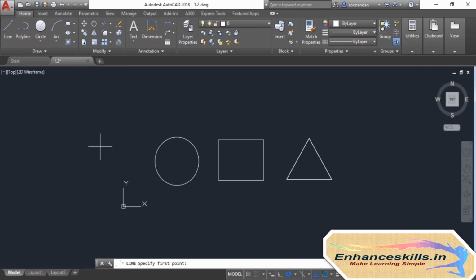Once the command is active, you'll notice that its name and also the instruction will be visible on the command line, and the cursor will change into this point selection cursor or into a pick box, which is similar to this. In order to exit this, simply press the Escape key. You can press Escape multiple times also if you want, and that will not make any change to the drawing.